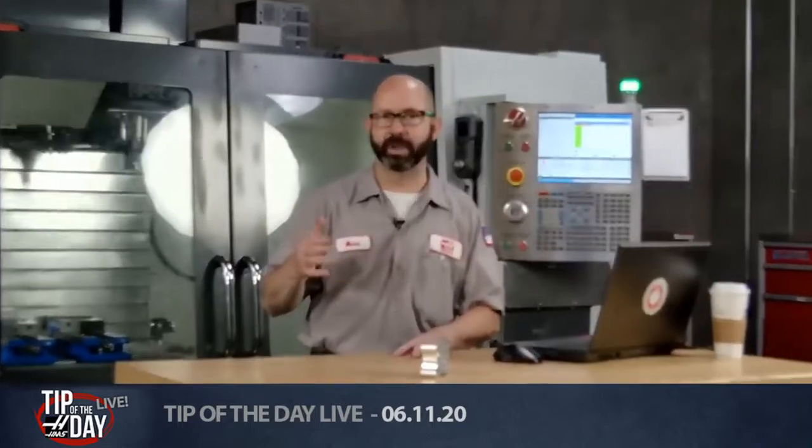And so the question is saying, why can't I program a G98? G98 on a lathe is different than a mill. G98 on a lathe is feed per minute, your inch per minute or millimeters per minute feed rate. Typically on a lathe, you'll program in G99, which is feed per revolution. And you can't program that way on the sub spindle directly. But here's the catch. You shouldn't be programming directly on the sub spindle anyhow. You're missing the point if you're programming that way.